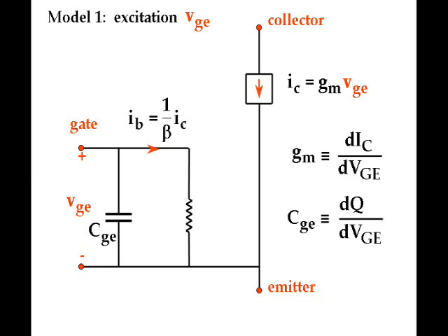The sole purpose in life of an equivalent circuit model is to give you the right answer. The small signal universal device model can be manipulated into many equivalent versions, choice of which is determined by advantages in obtaining certain answers. There is a choice of whether to include the capacitance within the manipulations or to leave it untouched outside the manipulations.